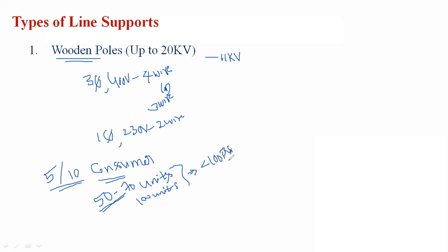But the electricity board needs to supply electricity to those consumers. Again, they need to erect distribution lines, a step down transformer, conductors and insulators. That burden is presented to the electricity board. So those areas prefer wooden poles, because wood is available in plenty at cheaper cost, and at the same time the burden on the electricity board is reduced.